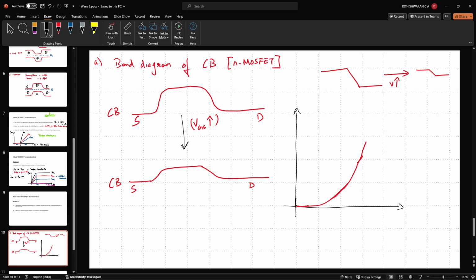again, I'm not going to say if it is higher or lower, at a different value of VDS, it might take a slightly higher VGS for me to achieve the same current. So if I'm looking at the variation of VGS and IDS, then this will happen for VDS1 and VDS2. Now I'm explicitly telling you what physical process is taking place here, so that should give you an idea as to which of these VDS is higher.